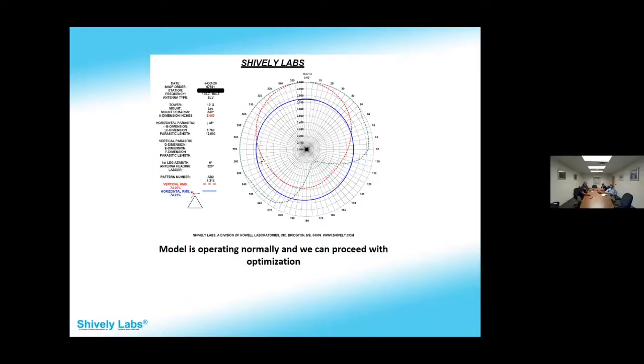Yeah, sure. And before you added the parasitics, theoretically, it's, at least as the FCC considers it, a non-directional antenna. How many people come to you and mount their non-directional antenna to know where the bulge is? That's one of those areas that everybody has to be very careful with. Optimization is acceptable to a certain degree.